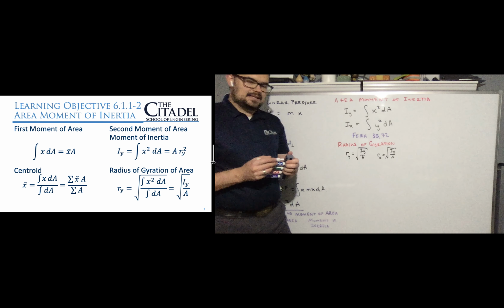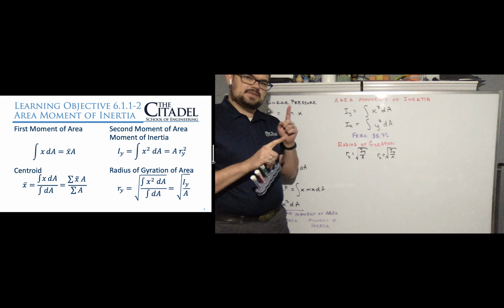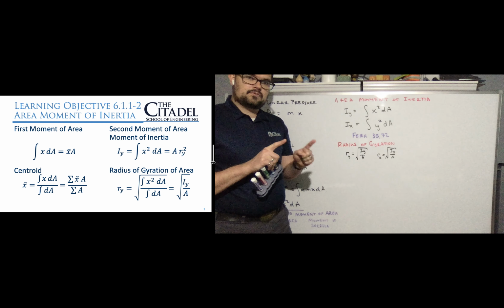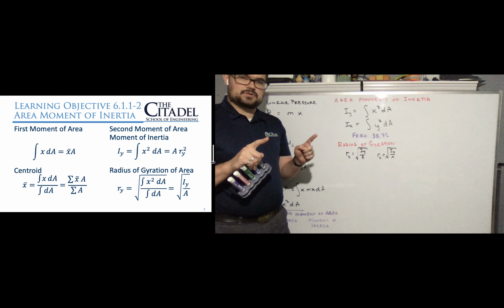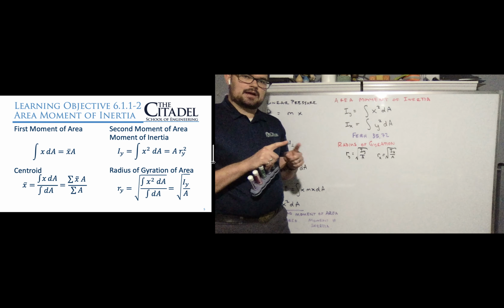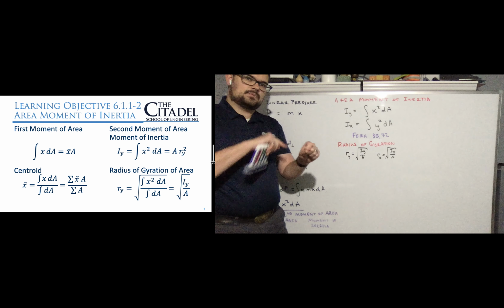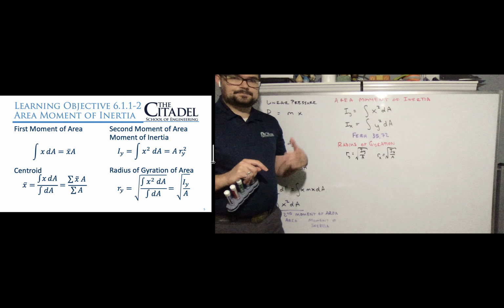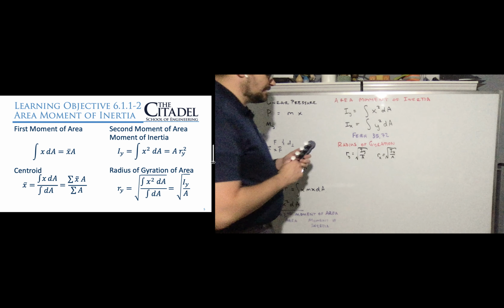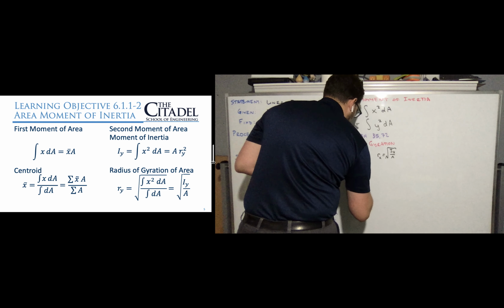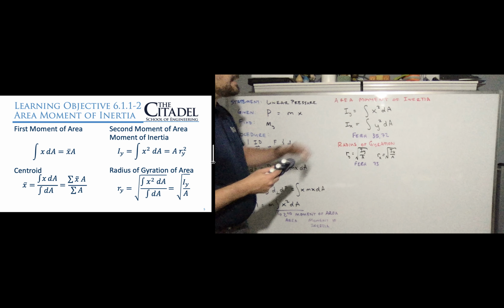And so the way you can think about this is that the radius of gyration is the distance from the center of gravity of the body, out to wherever the axis of rotation is, so either Ix or Iy, out to the center of mass, more or less, of where the material is as it would rotate. So moment of inertia, radius of gyration, those are thinking about rotational components. And this is on page 73 of your FE reference handbook.